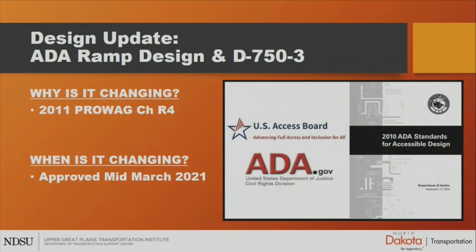And then why is it changing? So the nature of these ADA ramps is just ever changing. So updates to our standards were necessary just because things like vertical alignment, turning spaces, grade breaks, the widths of the sidewalks and all of those spaces, clear spaces, changes in direction. Those things are all outlined in Chapter 4 of PROWAG. Talks about supplementary technical requirements, and there's changes that have occurred there. And as far as definitions and things like that, we needed to update our standard drawing in that regard.